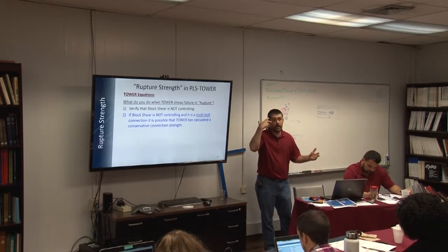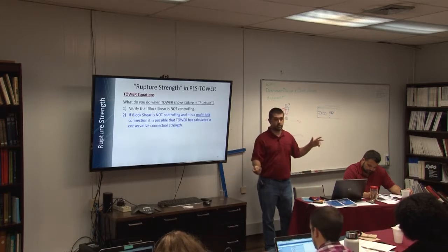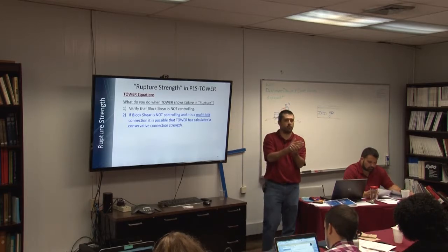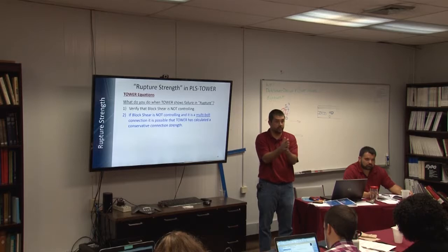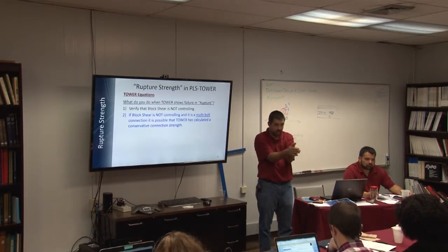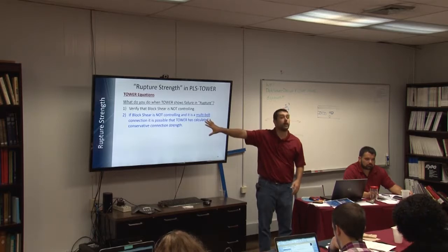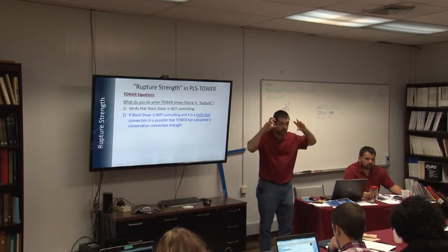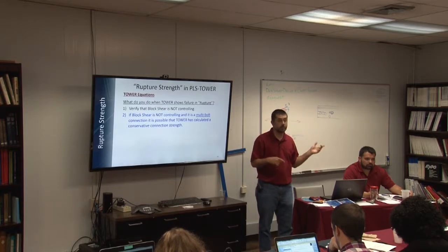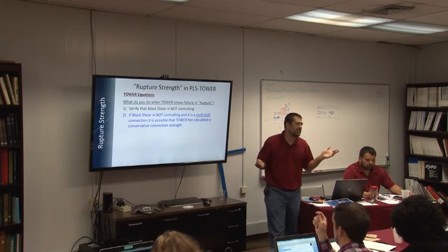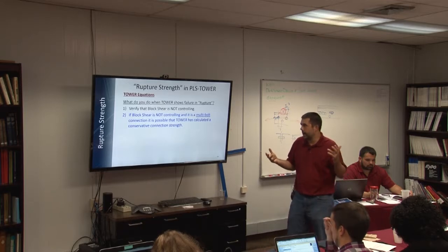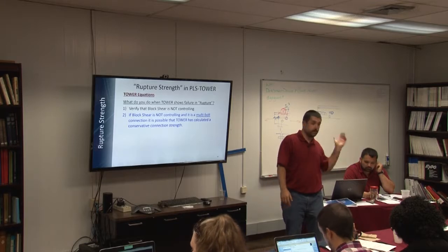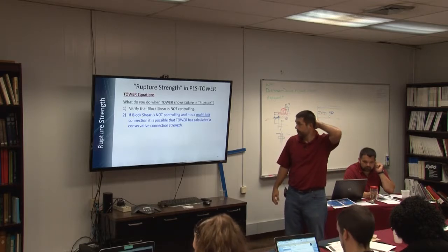Okay. But like I said, AISC, when I learned to design connections in school, they lumped bearing and tear out together. Like you looked at the bearing capacity of a bolt, the tear out capacity of a bolt, and you took the minimum of the two, and that was the strength of that individual bolt. What the program does is it looks at the total bearing connection and gives you a strength, and then it gives you the rupture connection and gives you a strength. So it's just different. I can't say that it's incorrect. It's a simplified method of what they're doing to meet these minimum spacings.